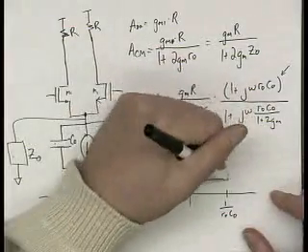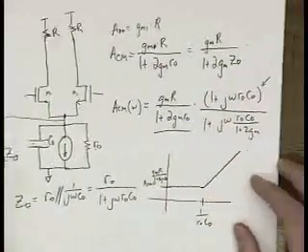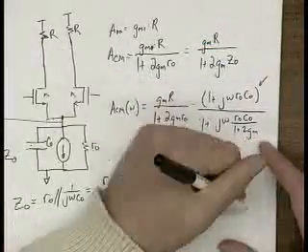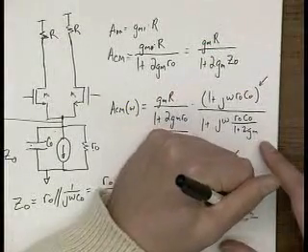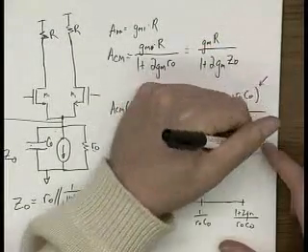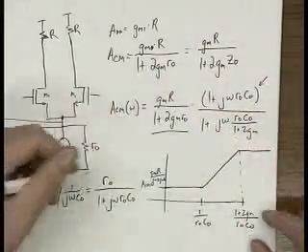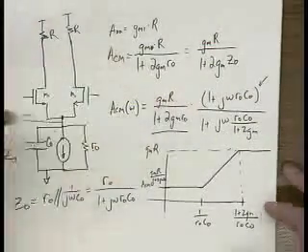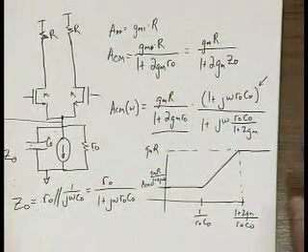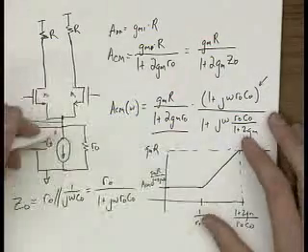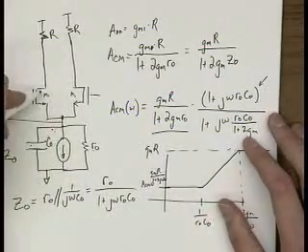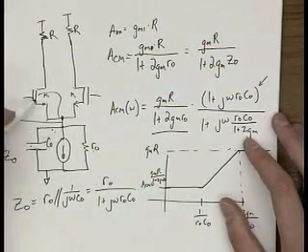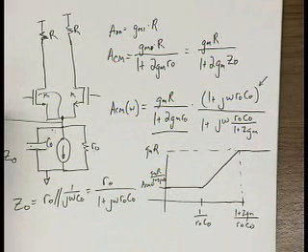So now at that frequency, the small signal common mode gain starts increasing. And then at high frequency, at (1 + 2gm) over R0C0, it balances out. If you calculate what that value is, you get gmR, which is what you would expect it to be at high frequency. So as you can see, you have a big capacitor here. Tying your source to bulk will minimize the VT of this, so it'll increase the common mode range of your input devices.